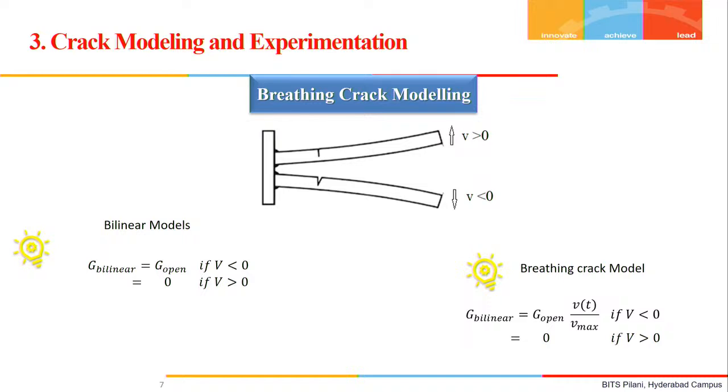In the second half of the cycle, where the crack is opening, the stiffness is a time-dependent parameter, so we'll get multiple frequencies, and by taking a harmonic mean of all those frequencies, we say that the beam is vibrating with one dominant frequency, which is the dominant frequency that we'll get later on. Interestingly, we have also found, when we did the forced vibration test, that the resonance is happening in the neighborhood of the dominant frequency. So that is what we are going to see.